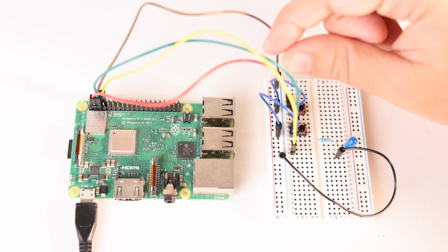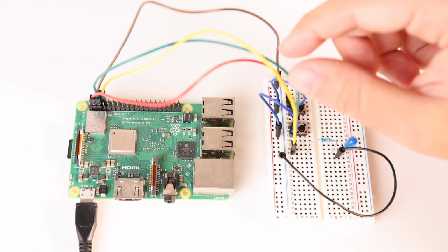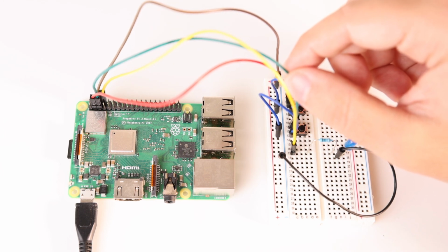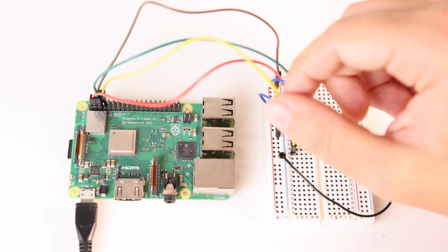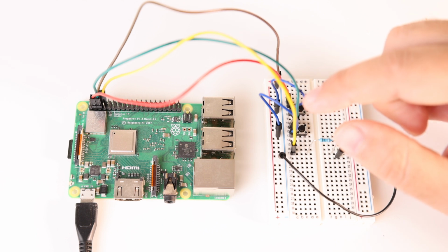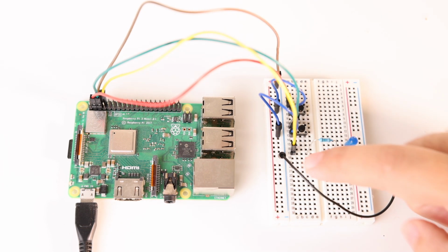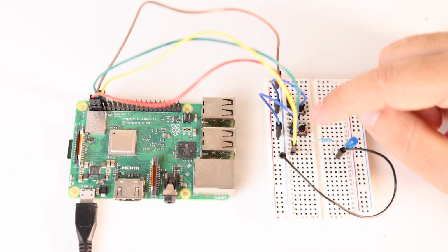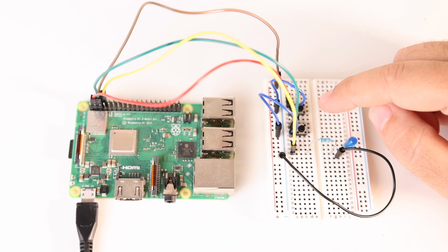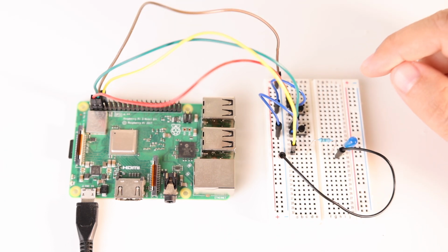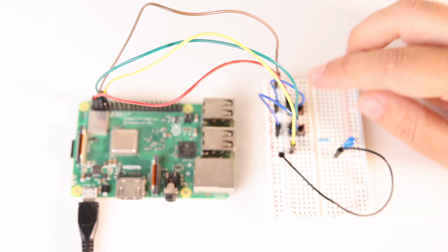PB1 is connected to the Raspberry Pi over this red wire on IX0.0. PB2 is connected also to the Raspberry Pi over this green wire on IX0.1. And my output here on the yellow wire going from QX0.0 to a resistor. Then on my LED goes back to ground. Right? The other end of both buttons are connected to ground because, as I explained, the Raspberry Pi has an internal pull-up resistor on both of these inputs. So let's see if that works.